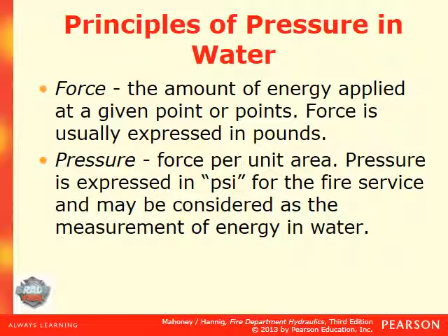So this all comes about, and to bring it full circle for those that don't know, the reason we're going over this is how much pressure is required at the fire truck to push out the water, from the hydrant in the ground, from the fire truck to the end of the nozzle to get the appropriate amount of water on the fire to extinguish it.